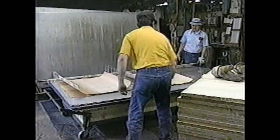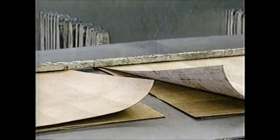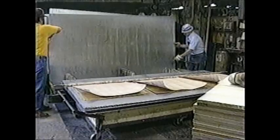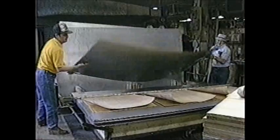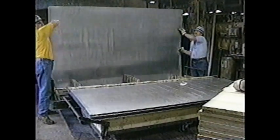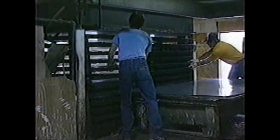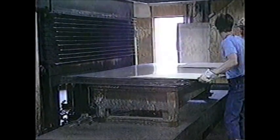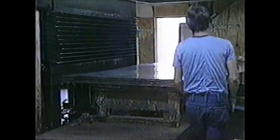Veneer plywood can be simply a face sheet, a core at right angles to the face, and a back with the grain parallel to the face. These 3-ply panels are placed between smooth aluminum panels known as cauls before being loaded into the hot press to be formed into 3-ply flat panels. When the press cycle is completed and the press opens, the cauls and panels are removed. The veneer panels are removed to cool and cure, and the cauls are stacked for reuse.